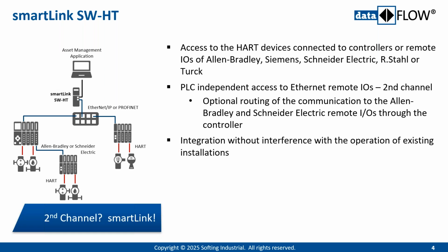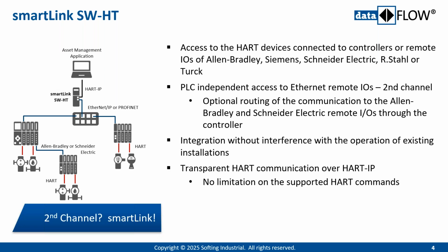The integration of the asset management application is without interference into the operational installation, so into your control process. So with the SmartLink SWHT, you connect to the Profinet network, and the SmartLink will then establish an additional communication to the CFU or the remote IO devices, and use this additional communication path to communicate with the HART devices.